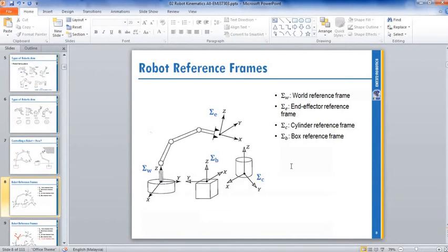Then we put in the program the orientation or the frame of your object. So we calculate the robot based on this orientation and also the gripper orientation. We can calculate using the homogeneous transformation and DH method to ensure that the gripper can position to align with this object to pick up.